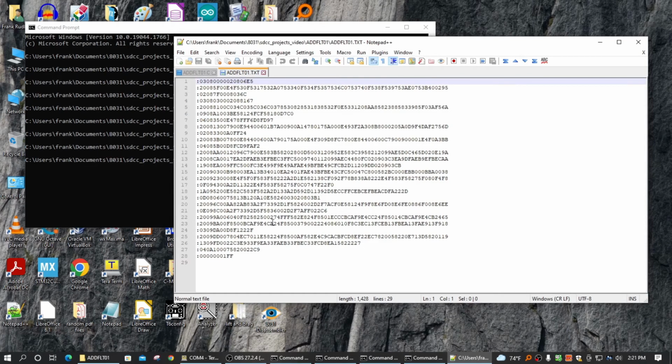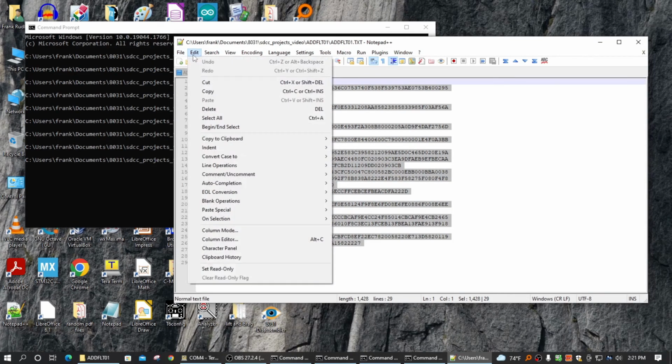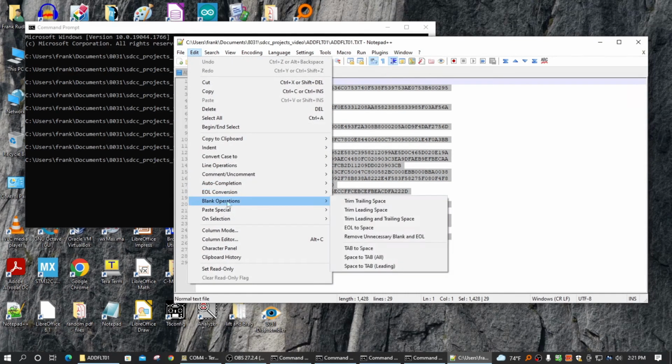So now it's a huge program just to add these two floating point numbers. See, there are libraries in the compiler that don't show up on the RST file. So the only way you can get it is by looking at the Intel hex file and disassembling it. So anyway, we're going to get this in the right format that I need to be able to load it.